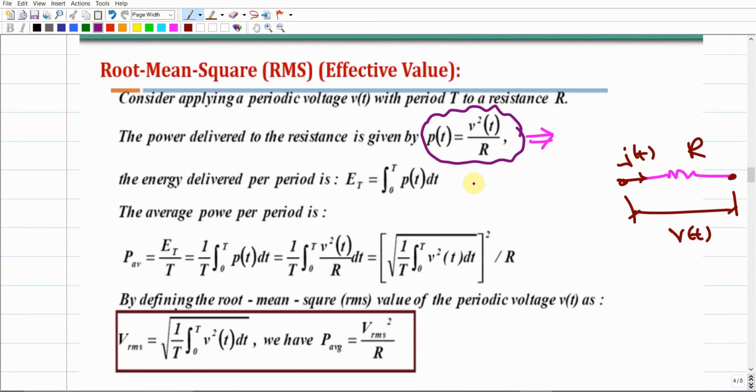It is highly acceptable to represent the power of an electrical circuit as the average of this varying power. The actual power is changing over time, but it is highly acceptable to take the average value to describe the equivalent power for this electrical circuit. And this is what we are interested in. What we are interested in for this slide is to show you how we can calculate the average electrical power for any electrical circuit with a sinusoidal voltage source.